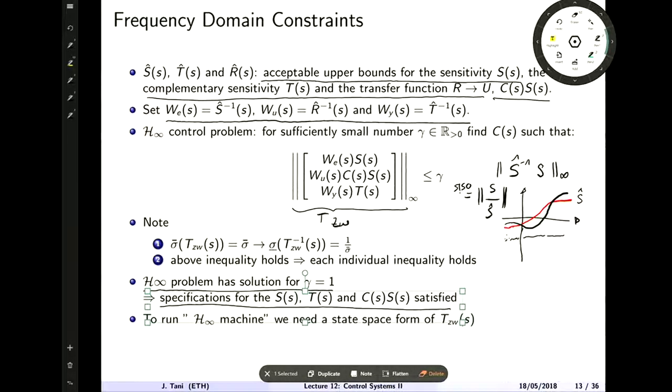So that's why you know that it should be small there. So it has to be smaller than 1. Yes, essentially, but maybe even smaller, because you don't want any amplification of disturbances. And then you also know that T, for instance, would state how the noise affects your output, right? And then you know that noise is at high frequencies, so you set a limit on T at high frequencies.